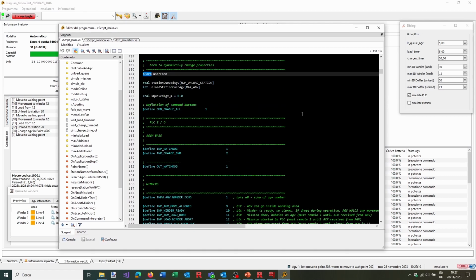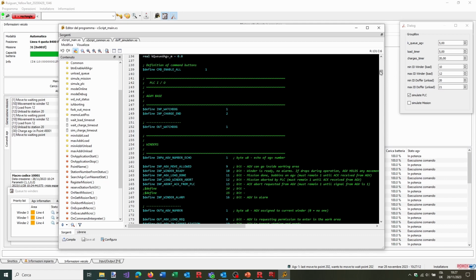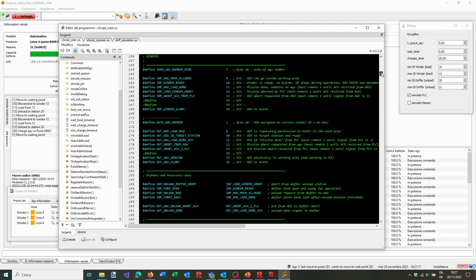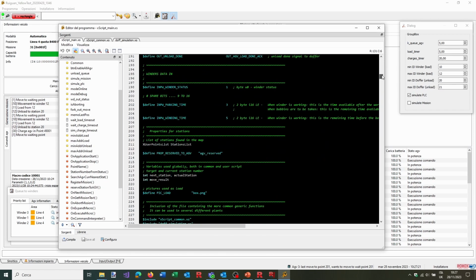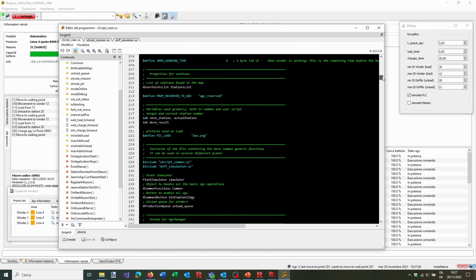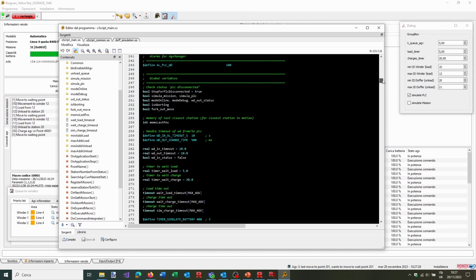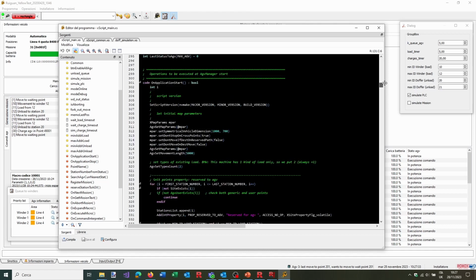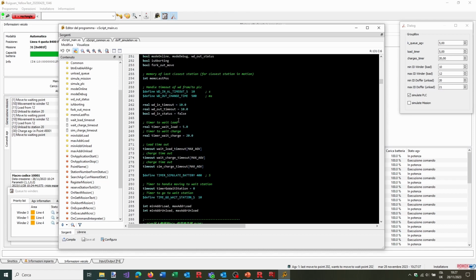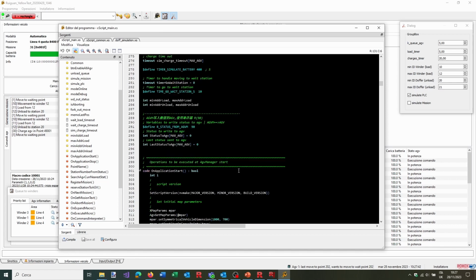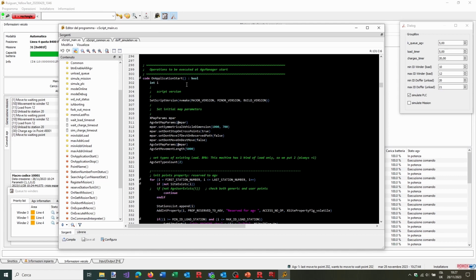Now let's go and keep an eye on this one. So here, this is a big code where I set some I/O. This is the I/O copied from the real plant from which I got this demo. Then some winder data. Then here some local variables local to the task that actually will be global to the system. You see, I can have a Boolean, real, integer variables. I can have some timeout variables, and here many others. And now let's begin talking about the application functions we have here inside.